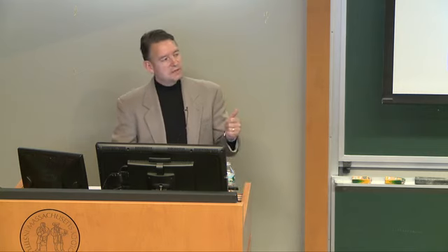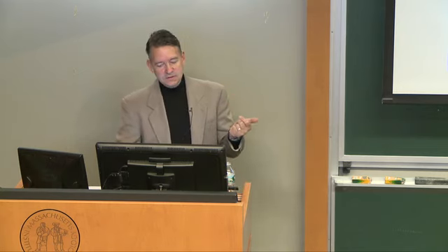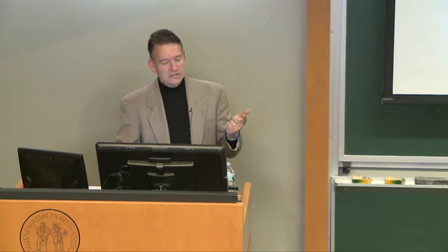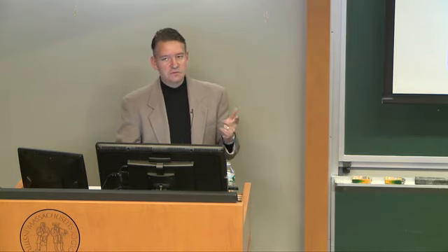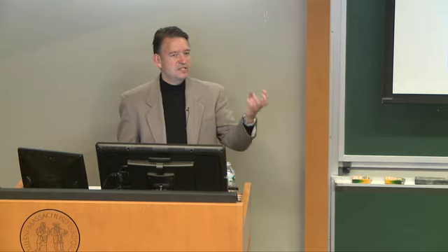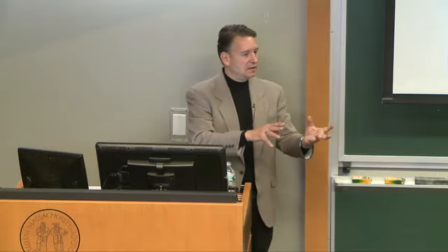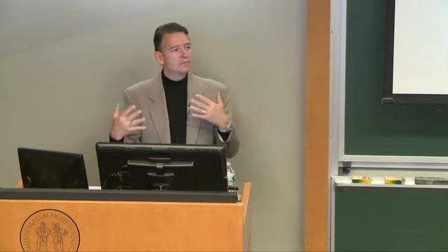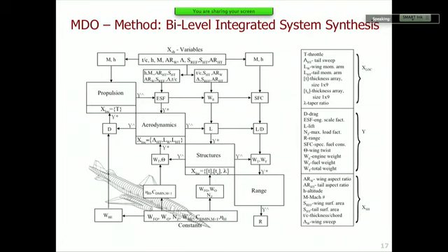So should you optimize the wing for lightness or for minimum displacement, or some mix of the two? The answer, of course, is it's a mix of the two. There'll be a sweet spot somewhere between a very stiff and very heavy wing and a very flexible, lightweight wing. There'll be some optimal mix of the two. And that's the key here.